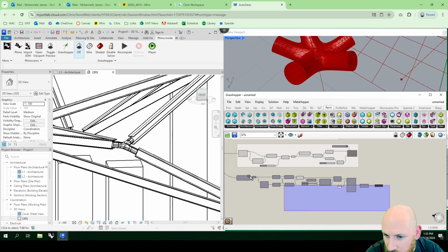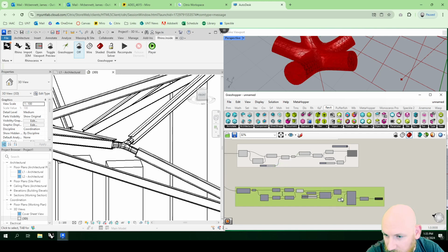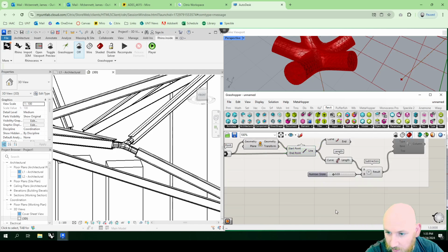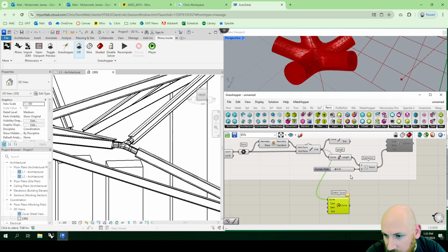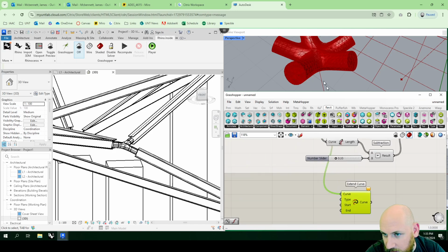Let's just do, firstly, make this into a group and move it down. I really did it into a group so that I can move it down all in one go. And from this line here, I might do extend, where I really want to shrink the curve, but extend, and then I can either do the entire length of the curve minus this amount.